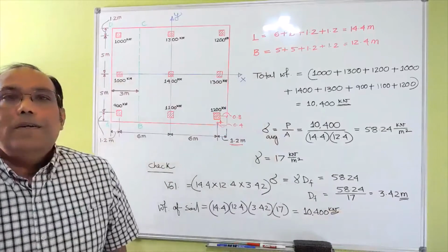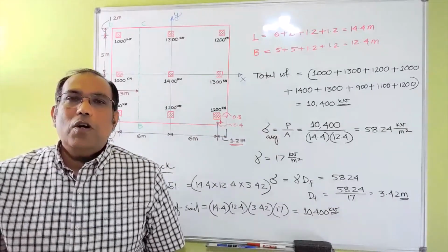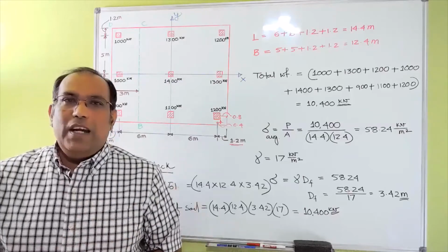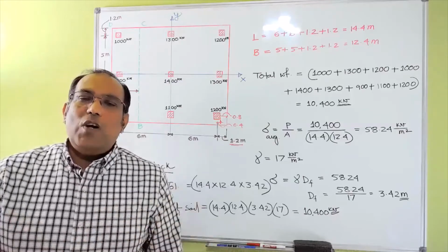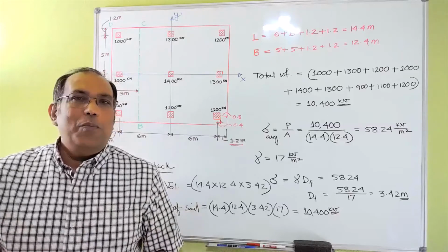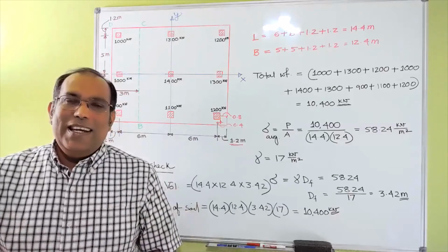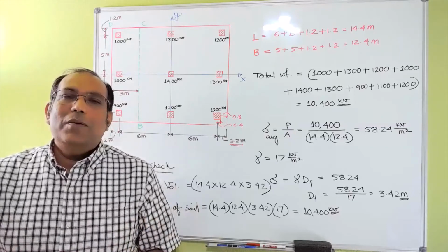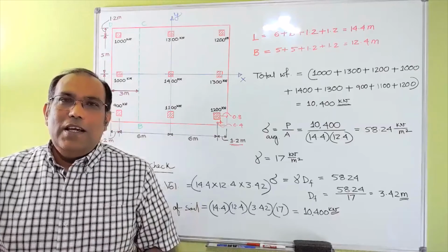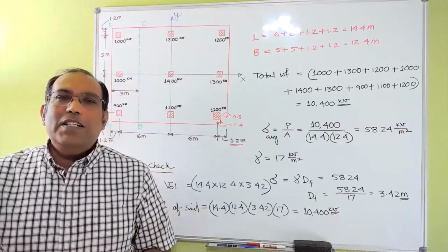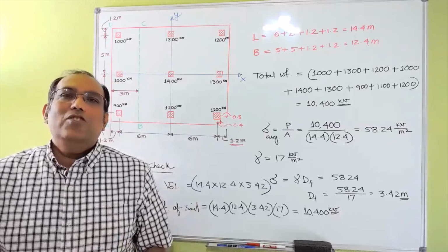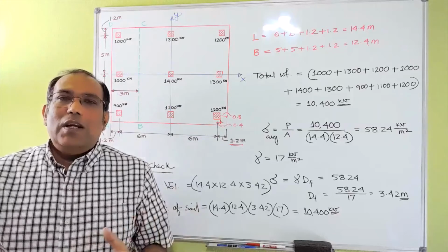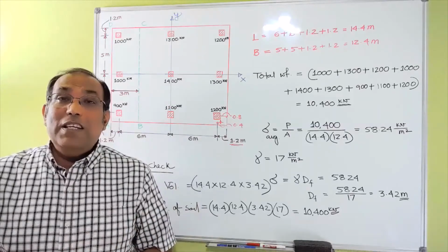kilonewton. So this means the total weight of the soil that you are taking out from there, you are putting the structure with the same weight. So basically the soil is not getting any increased pressure from the structure. And remember, for mat foundation this is important because in most cases we usually make a garage, underground parking or basement.